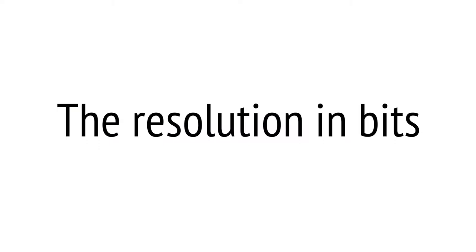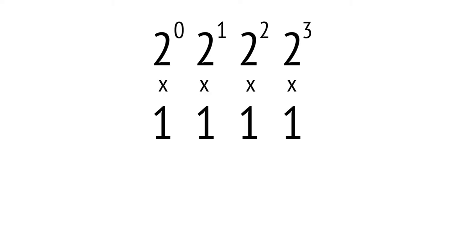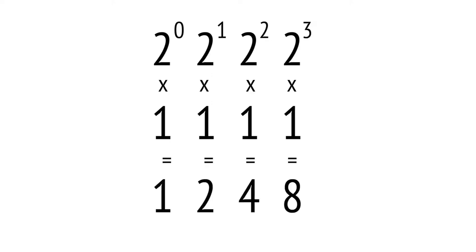The resolution is defined in bits, not in decimal numbers. For example, our converter with 16 stripes is 4 bits type. The highest digital number in 4 bits is 1111. It means we get 16 stripes from 0 to 15.